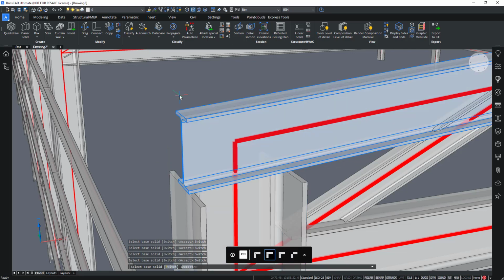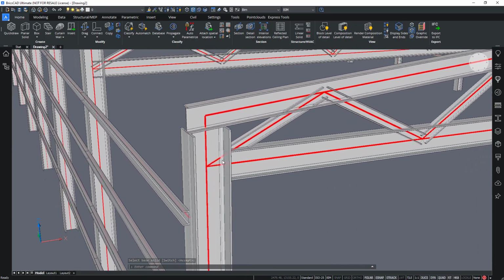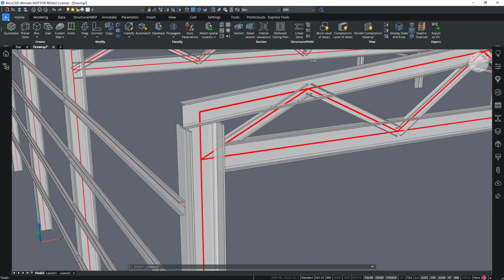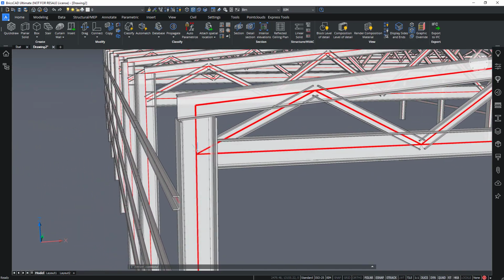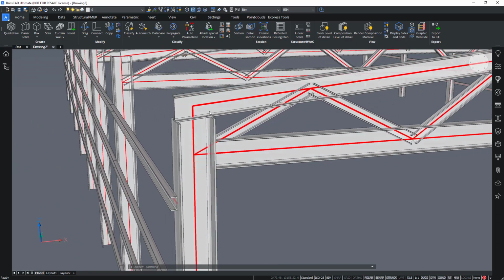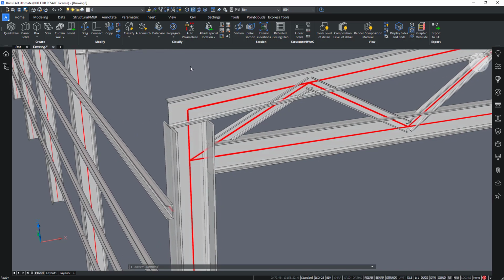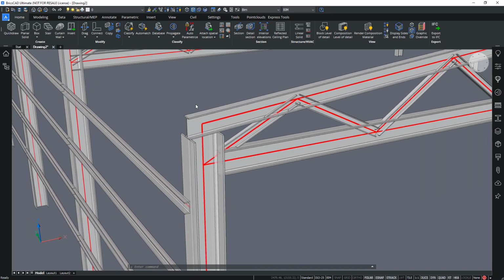Go for the second option. It doesn't actually change the geometry, but it only changes the axis here. Okay, let's assume this is the connection that we want. So of this node and this node here, we can actually combine all of this in one single detail for PROPAGATE to have it copied over to the rest of the drawing.